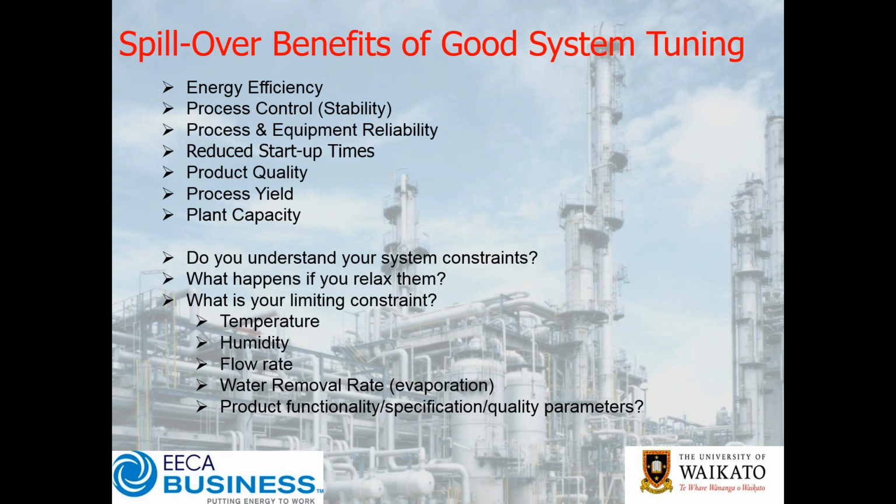Is there a temperature limit? Is there a humidity limit? Is there a flow rate limit? Is there a water removal or evaporation limit? Is there some other product functionality or specification or quality metric that we need to sustain, and that might actually put a limit on how far you can reduce things? Reducing airflow might save you some energy, or increasing airflow could give you more capacity and then give you better specific energy, but there will be a limit to how far you want to push that before you run into trouble, because it might then compromise some of these other metrics.